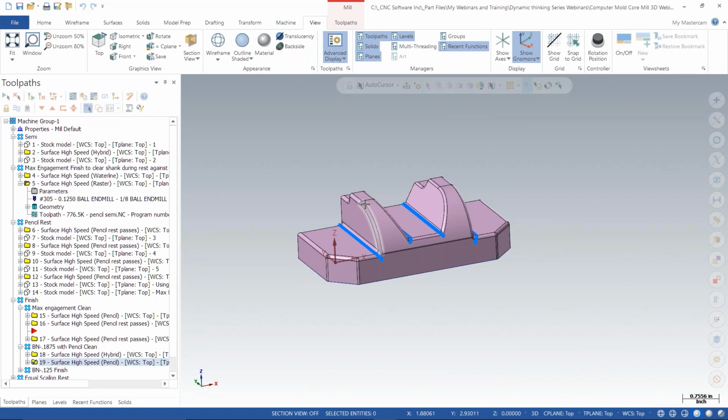And being able to place motion where you want. So hopefully all these concepts you saw today give you some additional tools to put motion where you want and to control your safe cutting conditions when you're getting into tight areas and smaller tools and such. Or if you want to be aggressive and rip a 1/2-inch end mill over something and then go in with some small eighth or quarter or some smaller tool and just do some nibbling. Sometimes it's simpler that way. So I hope all this helps.